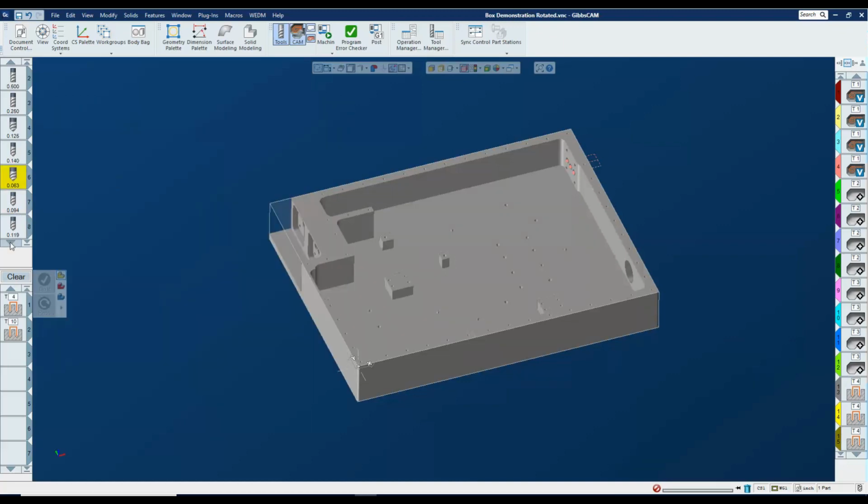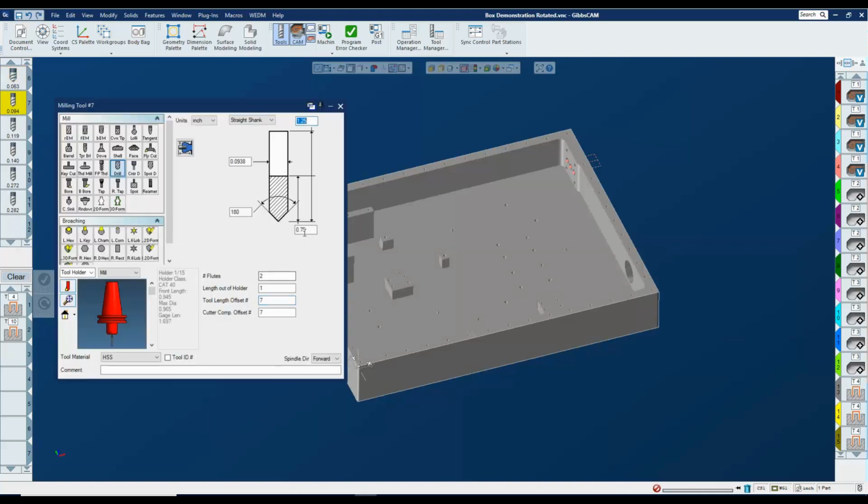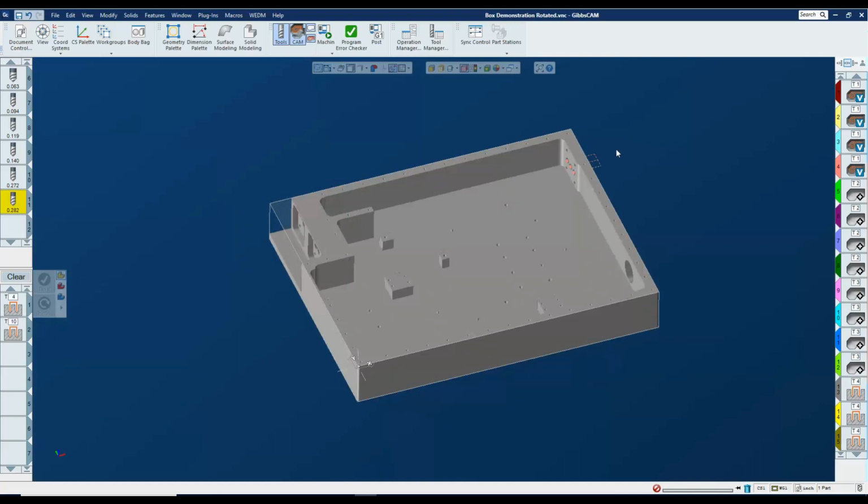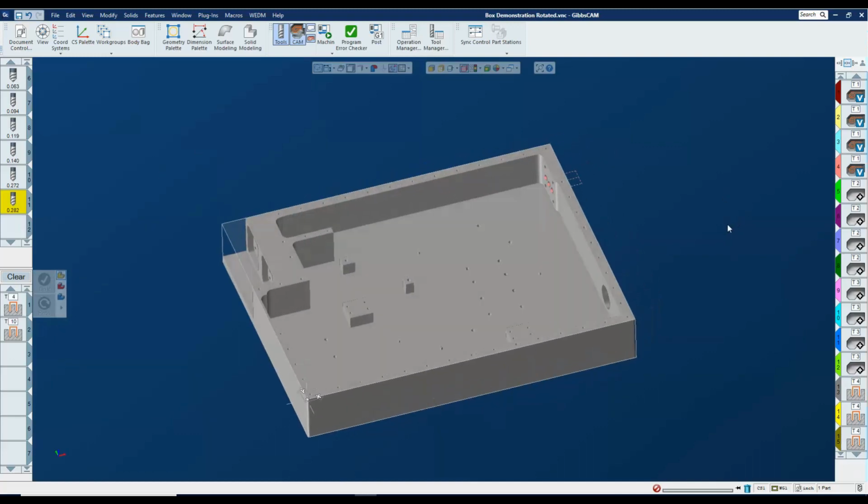And to look at the remaining tools, so we have 7, 8, 9, 10, 11. Let's just look at those right now. So we do have potentially some of the errors, but some of these tools only come in on the side and there's a lot less clearance needed. So this is set at 0.75, as you can see. Let's just look. This is only 0.5. This may be a problem, but I'm just kind of reviewing everything. 0.75, 0.75. But again, all of these, I believe, are only coming out on the second setup.